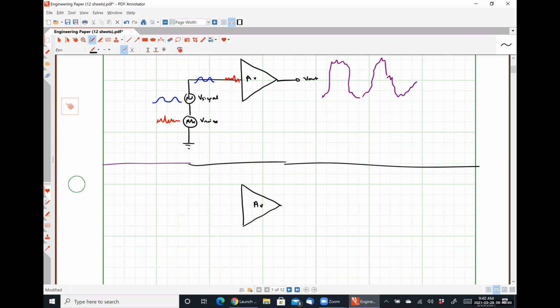We're going to have two input terminals, the VN1 and the VN2. And typically one of those input terminals is non-inverting and the other one is inverting. And that's pretty critical for what's called common mode rejection, which we'll talk about in much greater detail later on.